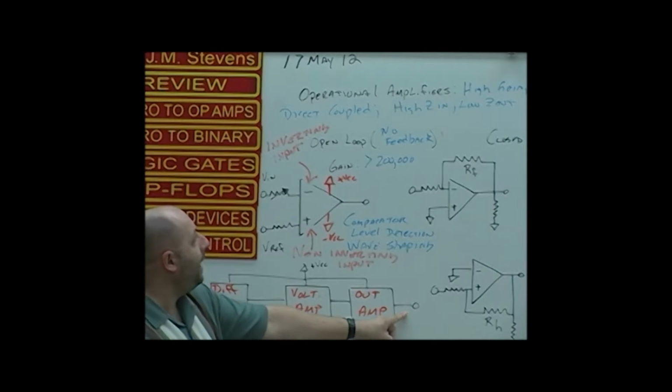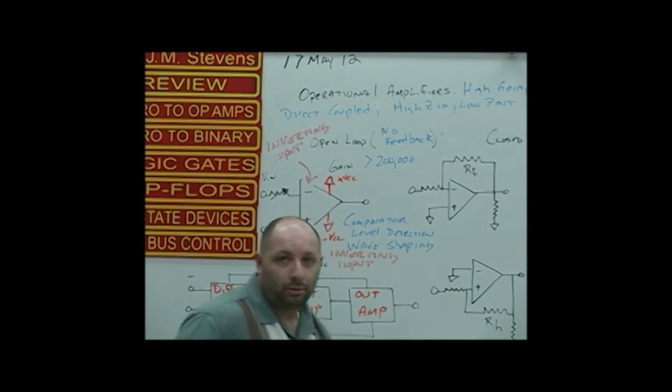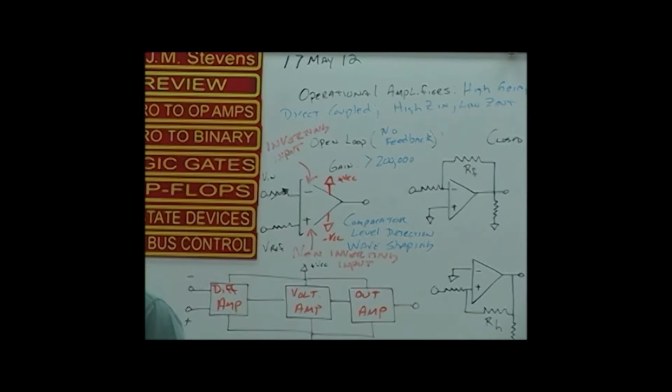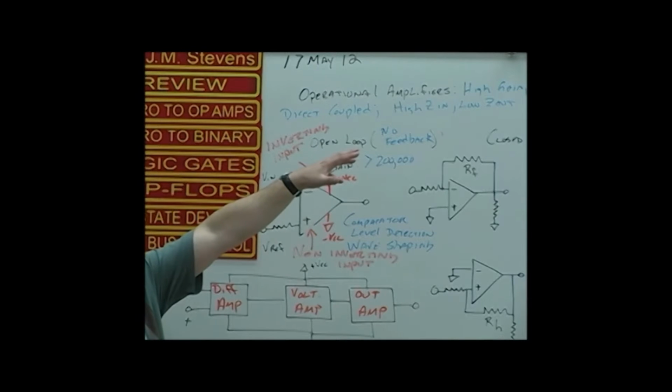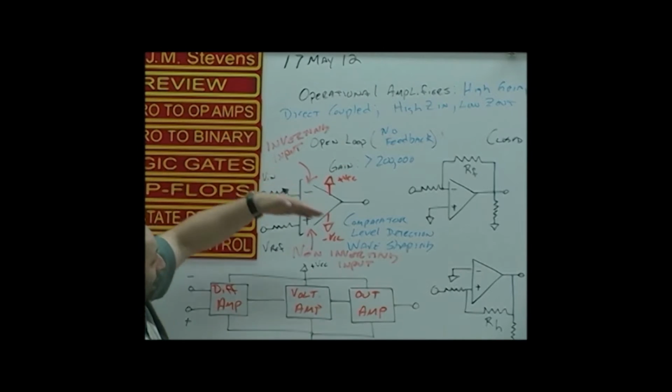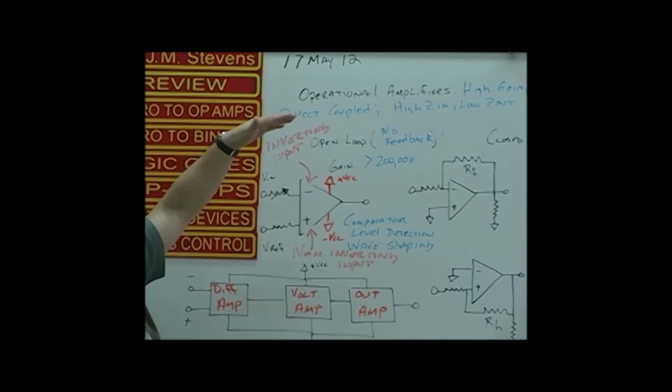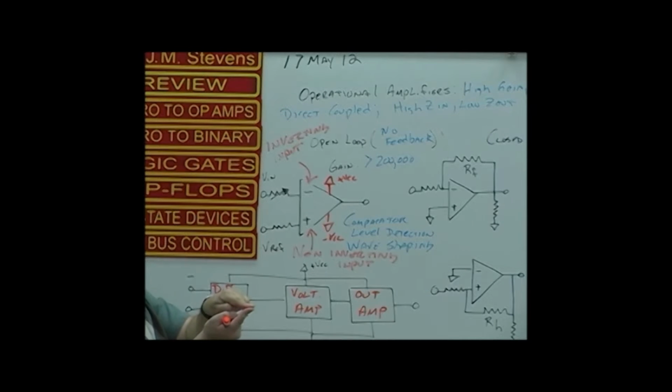Output. Why is the impedance low? Everybody remember? Yeah, it's a common collector configuration. Remember we looked at the internal workings of the chip, Q8 to Q9. That's where our rail comes from, positive, negative, common collector. The two emitters are tied together at the output. Whenever we're dealing with outputs on the emitters, the impedance is always going to be low. Just think about that already forward-biased emitter-base junction. Should make sense.